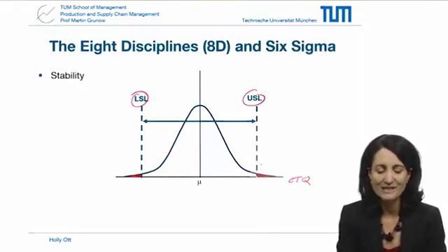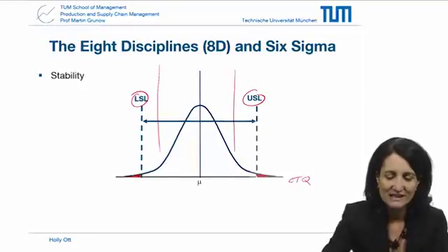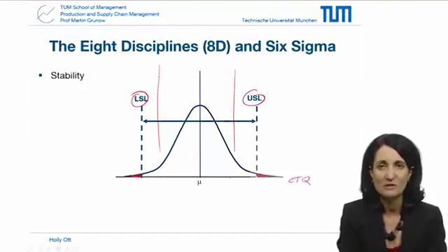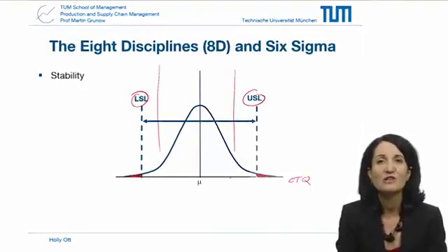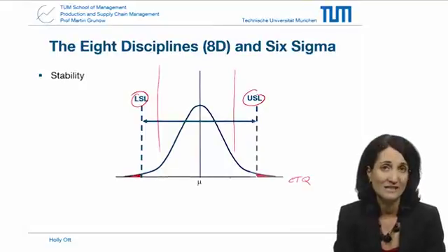I'm deliberately not drawing a control limit on this chart, but the idea is that the control limits would be spaced close enough so that if you're in control, you will not be out of spec. A stable, in-control process should be producing parts that are well within spec, meeting a high process capability.